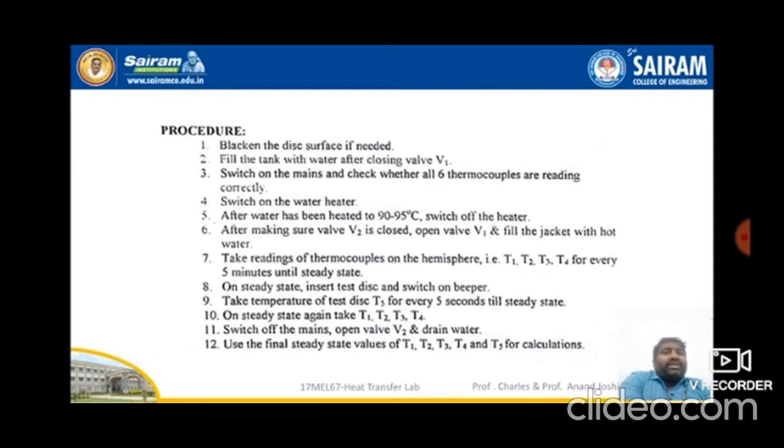Next, the seventh step is to take readings of the thermocouples on the hemisphere, that is T1, T2, T3, T4, every 5 minutes until you get steady state. The eighth step is, at steady state, insert the test disk and switch on the beeper.